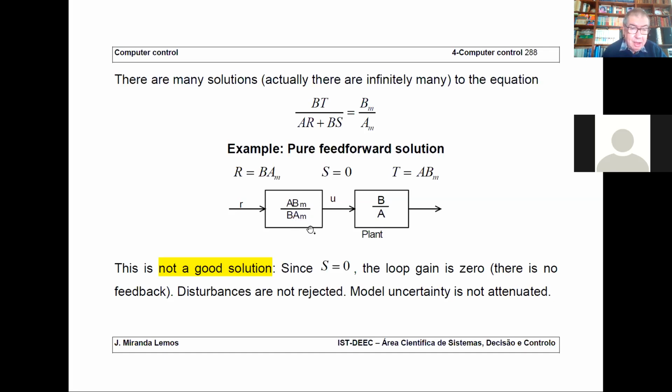It cancels from the input-output point of view. That's the meaning of the transfer function. But in the state model, it is there. So you have a state which is internal. It's probably causing you to go to infinity. And this state is unstable, causes an internal instability. So this solution that relies on no feedback and pole zero cancellation, that's rubbish.